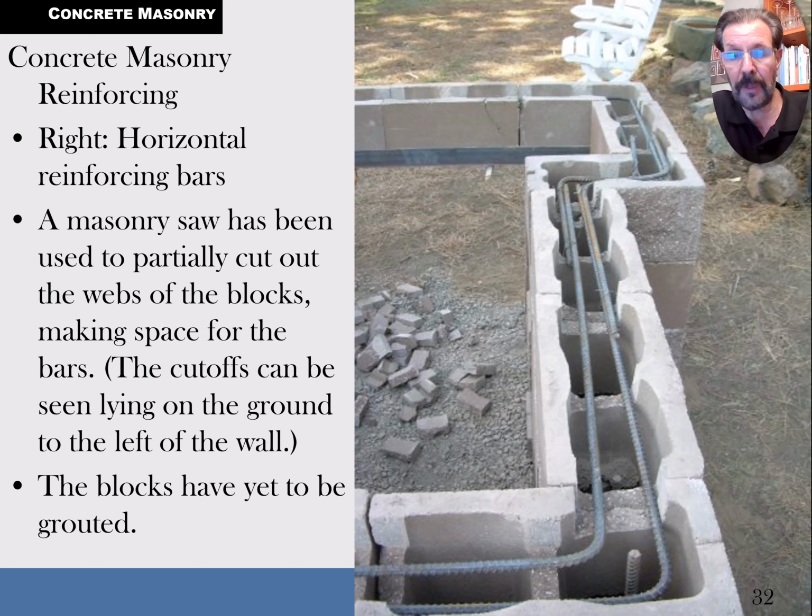So this one here, they were able to cut halfway through the blocks so that the block still holds together, and then they're ready to pour a beam. That's basically going to be like a 4-inch beam. They might even cut the block above and make it taller that way.